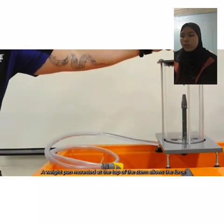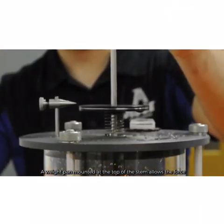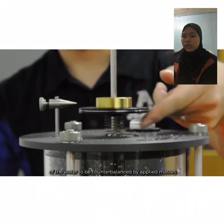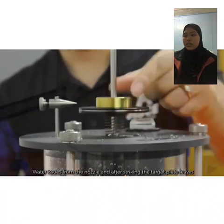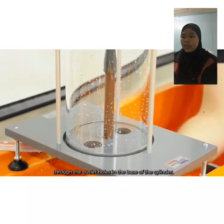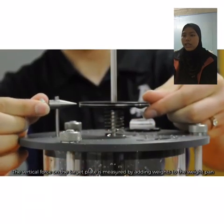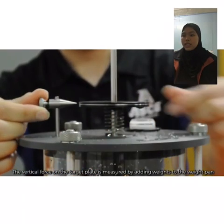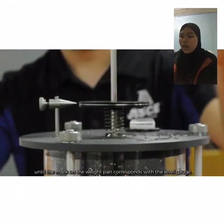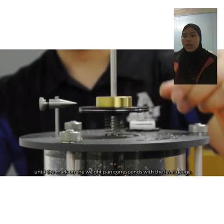Water enters a cylinder vertically through a nozzle and then strikes a target mounted on a stem. A weigh pan mounted at the top of the stem allows the force of the water to be counterbalanced by applied masses. The water issues from the nozzle, and after striking the target plate, leaves through the outlet holes in the base of the cylinder. The vertical force on the target plate is measured by adding weight to the weigh pan until the mark on the weigh pan corresponds with the level gauge.